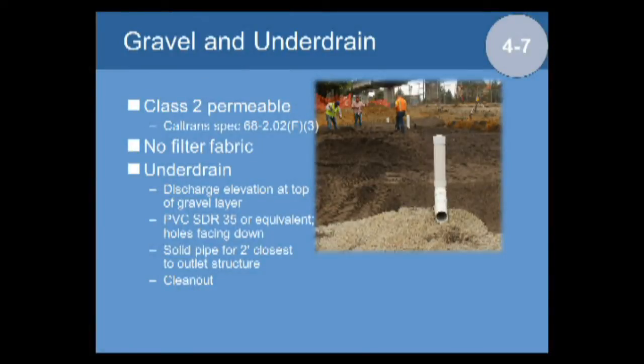The reason, almost all of them, in the cases of failure, was because there was a layer of filter fabric to keep the soil from migrating down into the gravel. It had gotten biological slime on it, had gotten clogged, and had stopped. Biological slime, it's great stuff. It processes pollutants. But it also clogs things and keeps runoff from getting through.